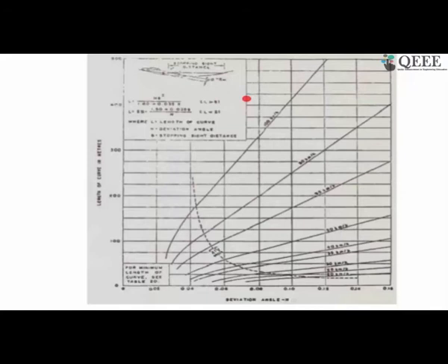The software is nowadays smart enough to tell you where it is not meeting the design criteria, and it will show you in red. As a design engineer you just need to see why it is not meeting, and accordingly change by trial and error, changing the PI location, fitting a different curve, or, if you need a design exemption from the speed point of view, all those things you need to do. So that is how it is being done.